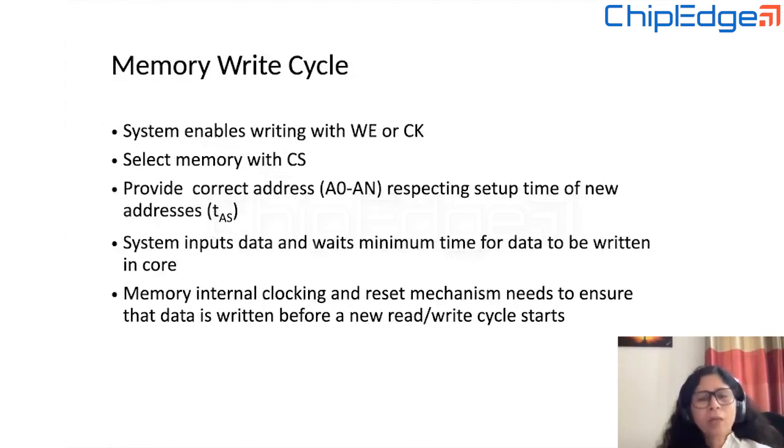Now, that time, how will the user know? The user will know through the memory data sheet, which is provided to the user. That once you do the write operation, once you provide the clock, how much time after that you need to wait to be sure that the data is written. Or sometimes with respect to address, this time is given, that once you stabilize the address, how much time you have to wait before being sure that the data is written. And then you can start the new operation. Suppose you want to write and then you want to read that data. So how much time after that can you do it?